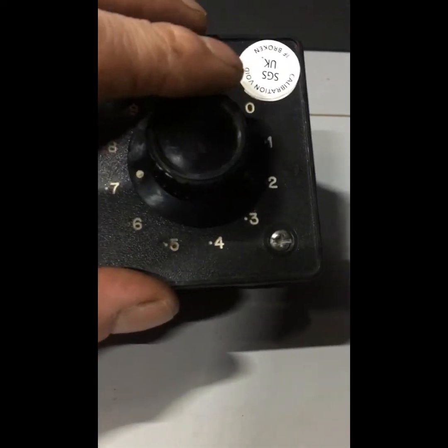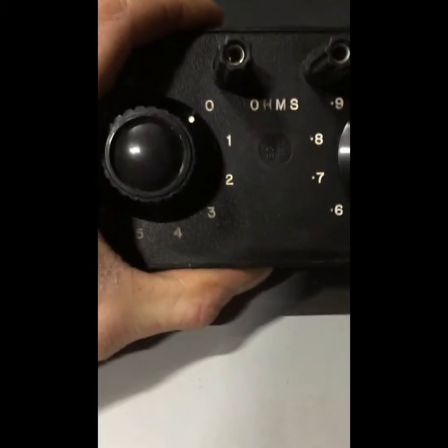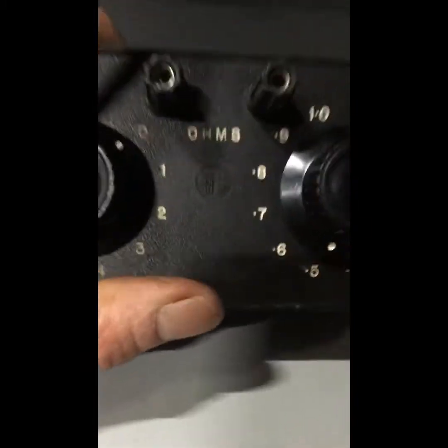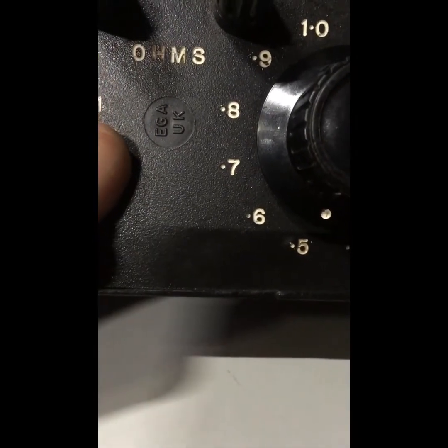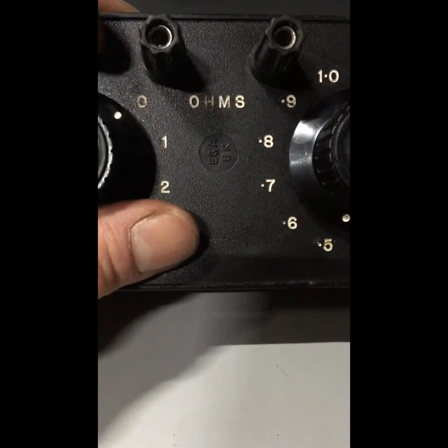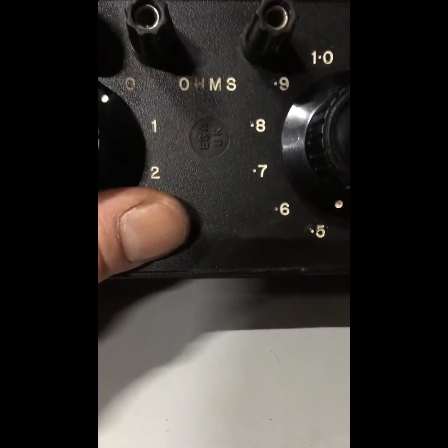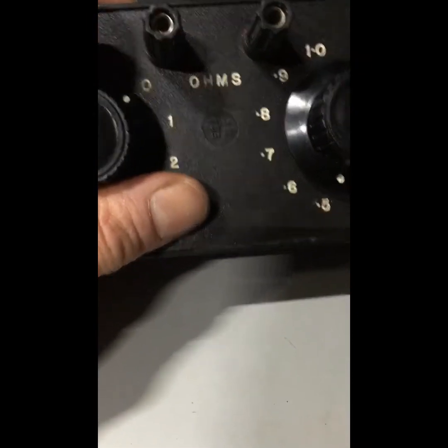There are differences between AC tracks and DC tracks. As I mentioned, we don't want our shunt to go below 0.5, and we're aiming for a good pick of 1 ohm. Another little key thing to remember is we also want a pickup value, and the pickup value is nominally double the drop value. So if the drop that de-energizes a track is say 1 ohm, the pick will be around about 2 ohms.